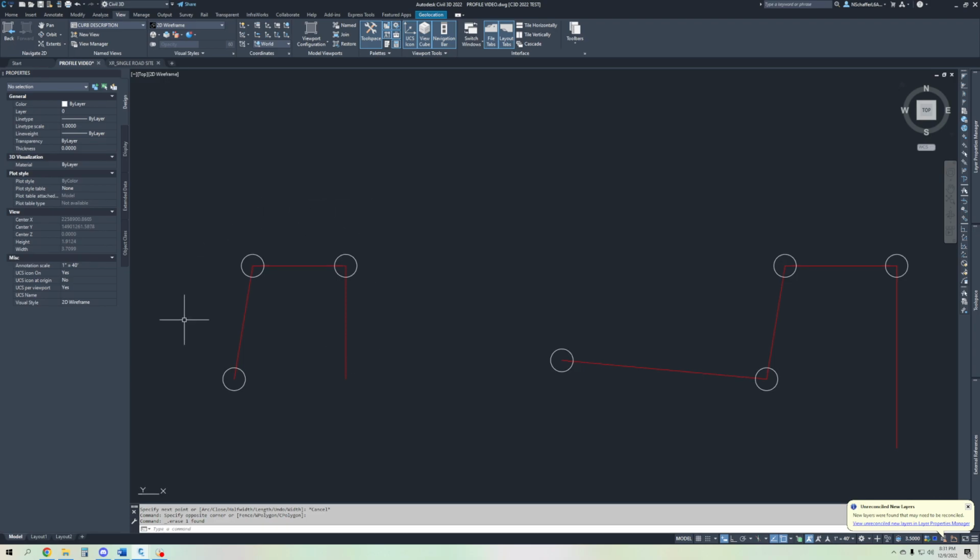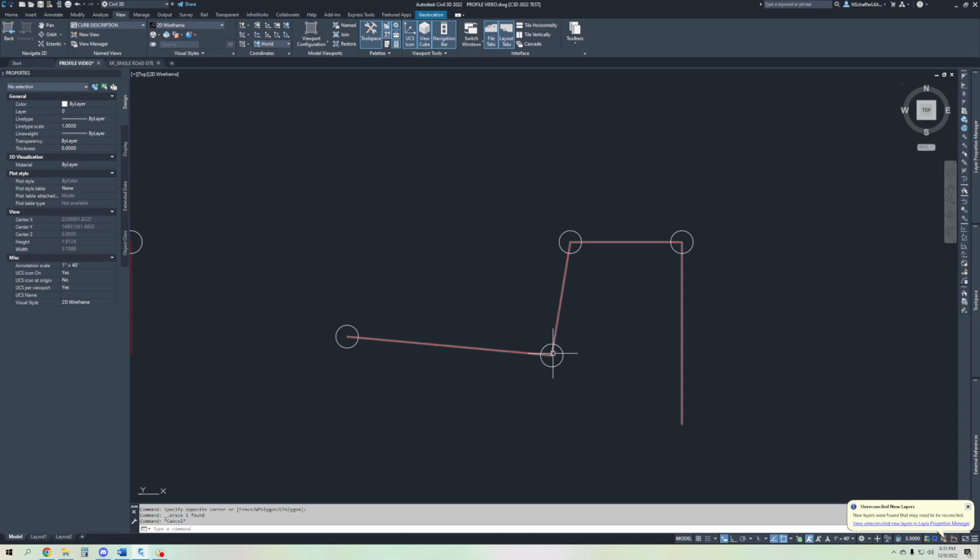So that is this type of curb. This would be a median curb, and then this will be a curb and gutter. So this is the gutter pan that water would be flowing through. So this point here, so I draw a point here, point here, point here, and a point there. This is going to be my lip of the gutter. This is going to be, again, my bottom front face of curb, top front face of curb, top back of curb. So I would go through and draw all of these points.